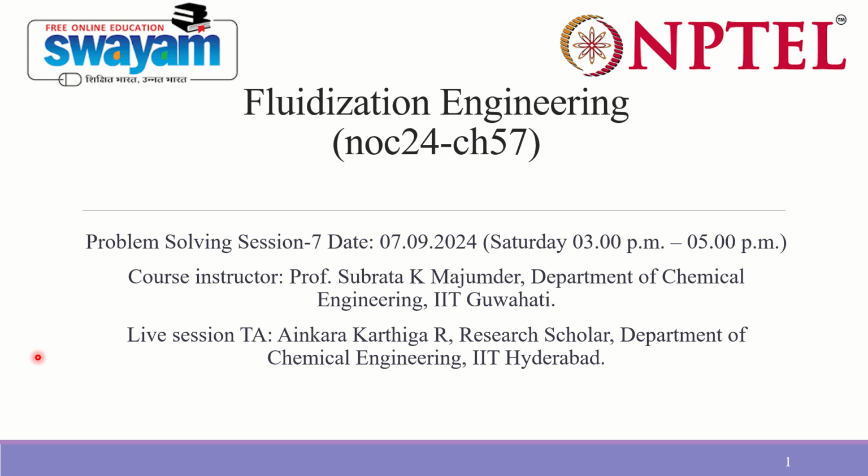Because in fluidized beds, we pass the fluid inside the packed bed at a sufficiently higher velocity. In that case, the particles start to move, and when these particles move, they behave as fluid. That's why we call them fluidized beds.